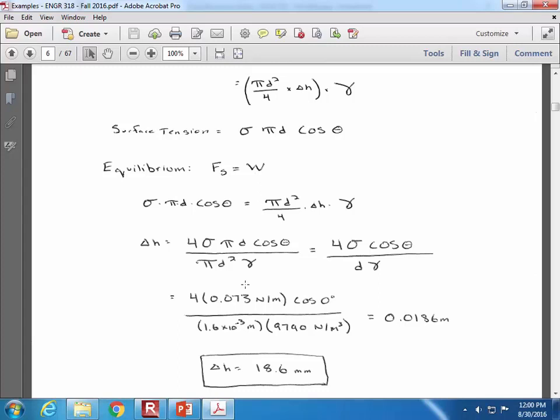But there is some soil moisture even above the water table. The water table is where all of the soil voids are full of water. But these little connected soil grains, if there happens to be a collection of them small enough in diameter, interconnected soil voids, then water is drawn up above the water table, and so the roots from a tree don't have to go all the way down to the water table. They just have to make contact with what's known as the capillary zone because of the capillary effect.